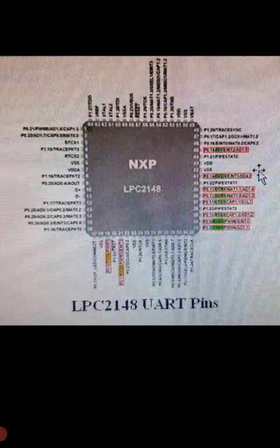The second register is the UART0 transmit holding register. It is an 8-bit write-only register, and the data to be transmitted is written to the register. It contains the newest byte and the transmit FIFO. The divisor latch access bit must be 0 in order to access the U0THR.